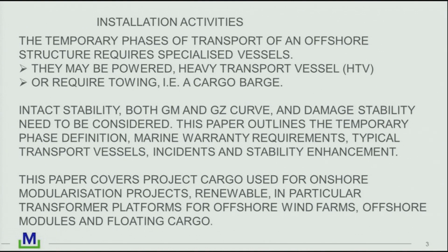There are three main phases in the installation of an offshore structure or the delivery of a module from one yard to another onshore site. So that's the loadout, the ocean transport, and then a float over or lifting offshore or a load in back at the final location.